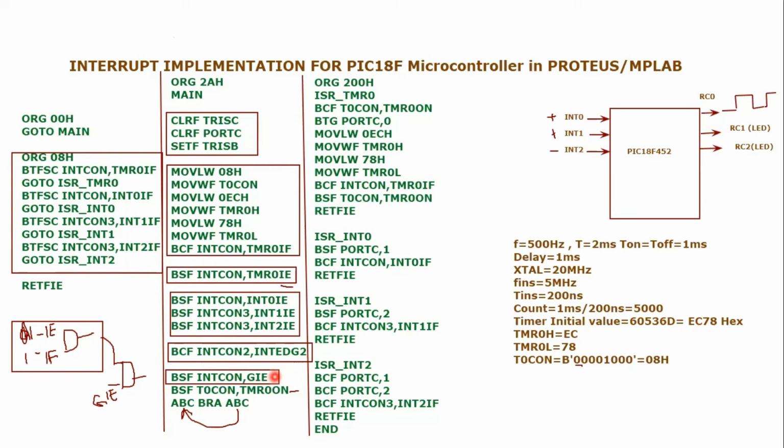That means because he is going to already serve one of the interrupts, he cannot entertain any other interrupt. That is why GIE is disabled, so that there won't be any further interrupts, right? But we have realized that that was a false alarm, so we are returning back to the main code, and we need to enable it again. So this retfi instruction does both things, right? It will return to the main code and it will also enable this GIE. That is why I'm using retfi.